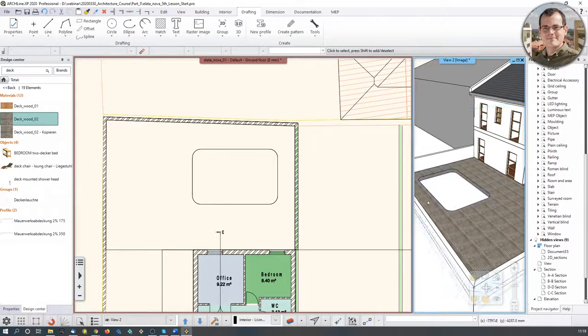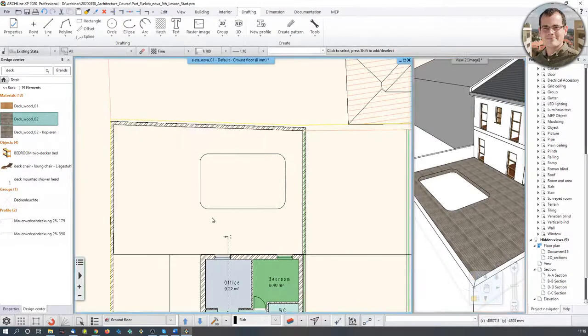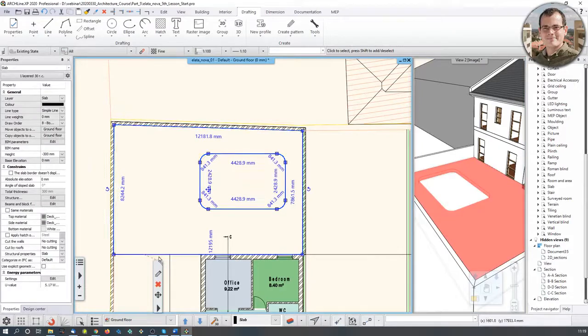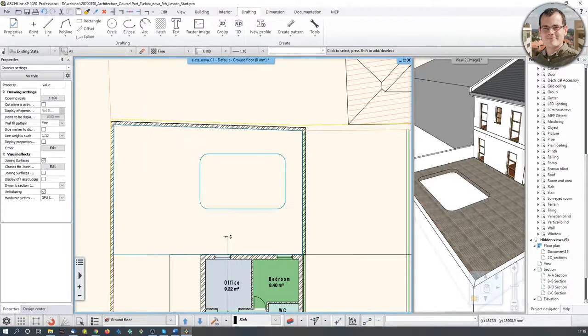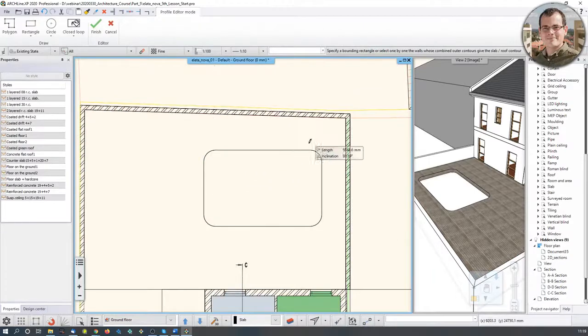So the problem with this is that there's nothing under it. So there's nothing to signify water. So how do we do that? For this, we need to have another piece of slab in here. And the way we sketch it, we click on the existing slab, right click, say create similar, and we start sketching the next slab, tracking the contour.